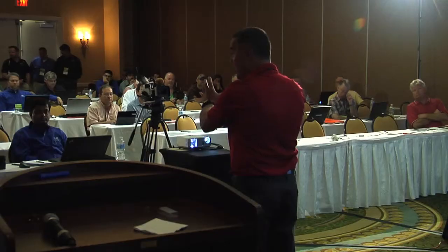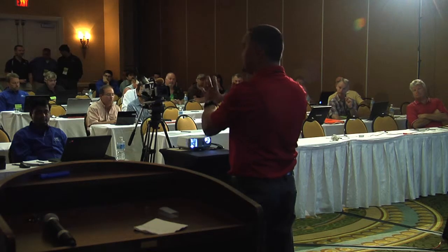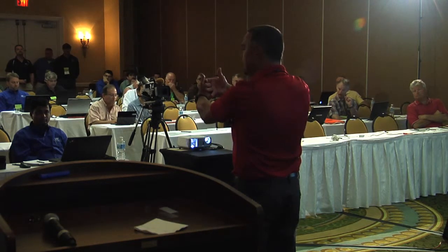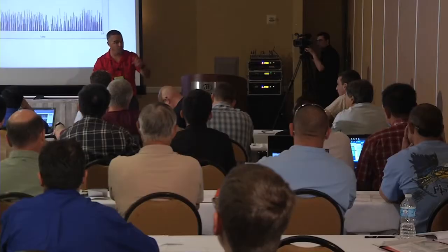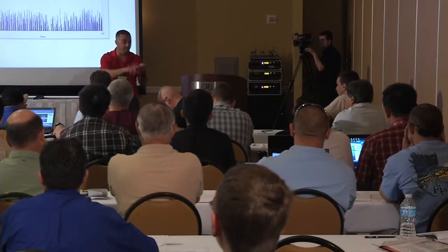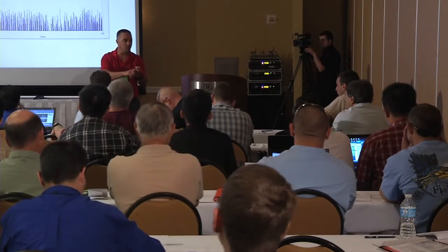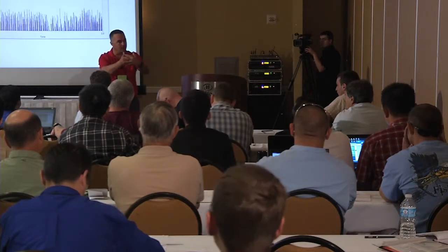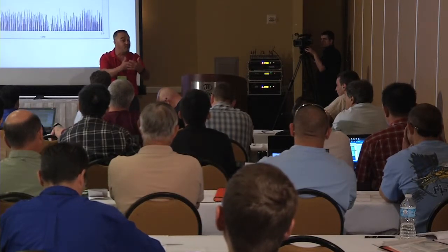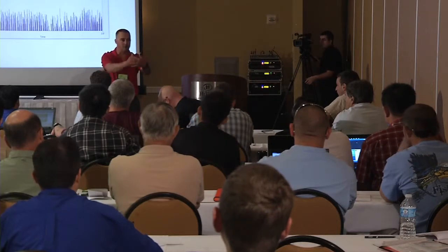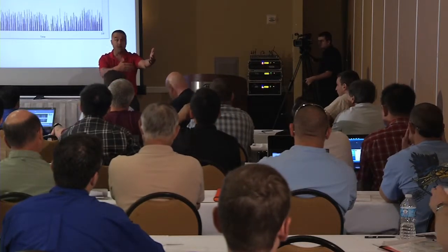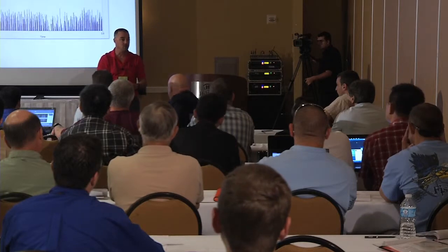Yes, sir. The question was, with the overlay, what does that really tell me, correct? What value is that? For me, it's two things. Number one, I can say, here's something we know was proved to be a tracking event. And on top of that, I've superimposed with the overlay my recording. So the two things I'm looking for in the FFT are frequency peaks and frequency noise or content in between the harmonic markers. By utilizing the overlay, I can show the similarities between my recording and a known sample that tells me I have an electrical fault in nature.